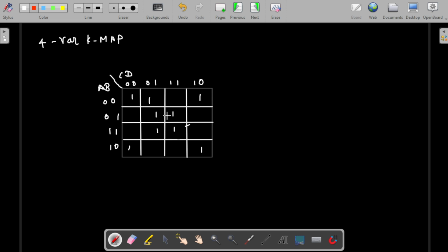As we know, the priority is 4, so I am taking the middle one, 4 here. That's the first one. Another 4 possibilities are also there, which you may miss: the corner ones, so all the corners are also mapped together. Adjacency means this also. When we fold this K-map, the variables that intersect can be taken into a group. If we fold this one, this 2 2 will map here. If we fold this one, this 1 1, this 2 will also map here. That's what we're mentioning.